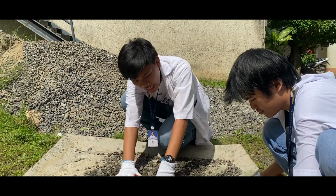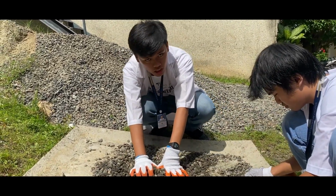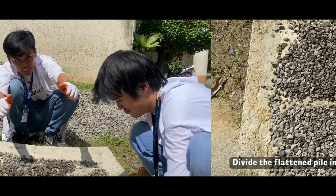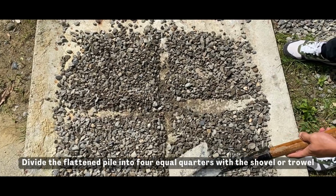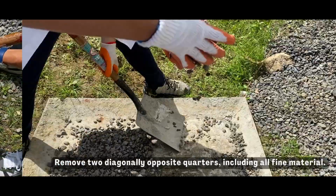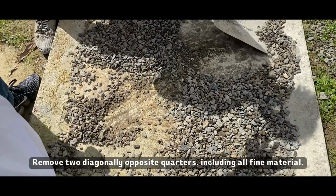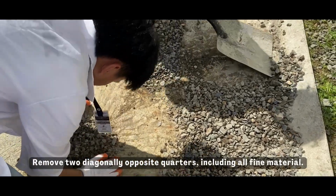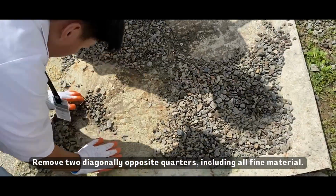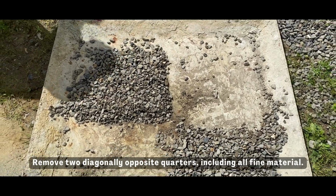Spread it evenly and divide it into 4 quarters. Divide the flattened pile into 4 equal quarters with a shovel or trowel. Remove 2 diagonally opposite quarters, including all fine material. Lastly, successively mix and quarter the remaining material in the same fashion as the original sample. Continue this process until the desired quantity is obtained.